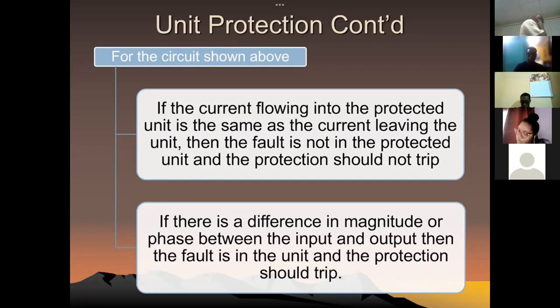So again, I'm trying to remember, I think you're the group I was talking to about the magnetizing curve. I think so. All right. But there's a property, we talk about retentivity, which is an important property for your transformers. When you de-energize a transformer, the transformer will maintain some magnetism in its core. So in terms of the core of your transformer, what you want is that it should be easily magnetized and should not readily lose its magnetism.